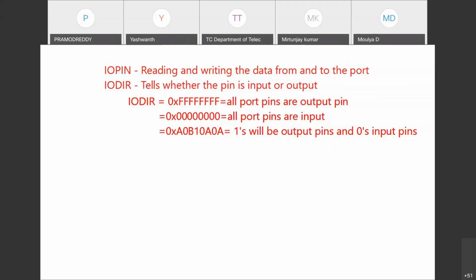It clears the pin into low state, meaning it clears the content. A small understanding is required. Whichever pins you set as high can be made low if you put the same value of the IO set into IO clear. Please understand the slight difference over here.